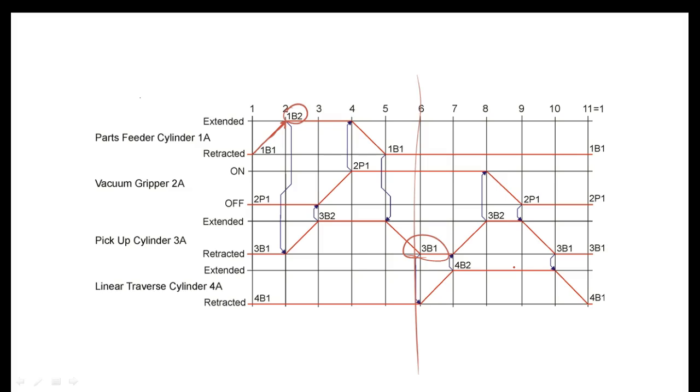Right? You understand? So you're saying it'd be like trying to fix a car if you don't know how to crank it. If it stops right there where you just drew the line, you make sure 3B2 is false, 3B1 is true, correct? Well, we got this far right here. So what we would do is make sure this guy right here is indicating it's what? Retracted, right? And this guy right here, so 3B1 should be true, and 3B2 what? So this would be your problem right here. I told you this would probably be the problem right here.